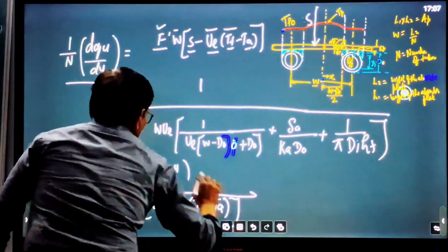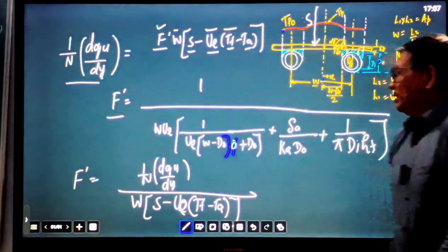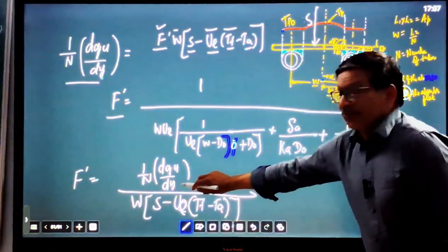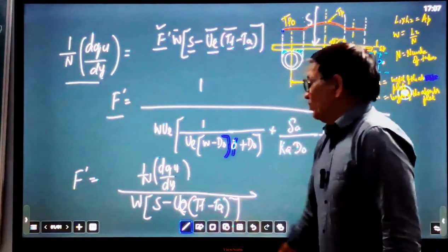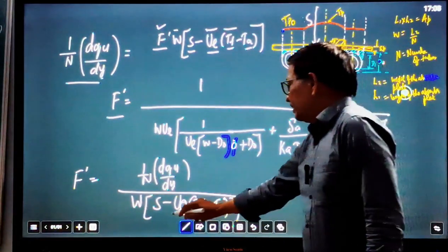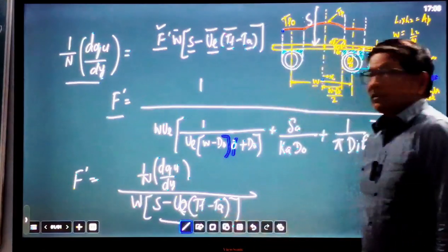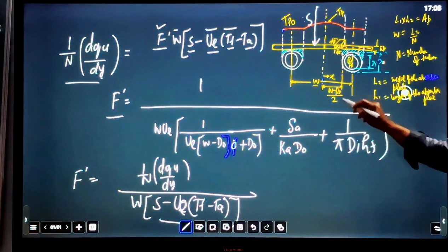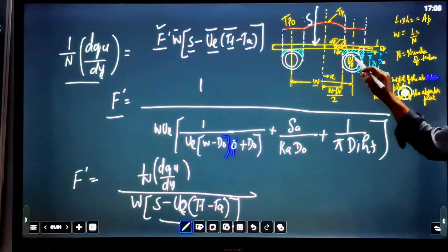So it is the ratio of useful heat gain per unit length per tube to the useful heat gain when the collector plate temperature equals the fluid temperature.